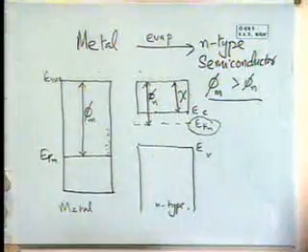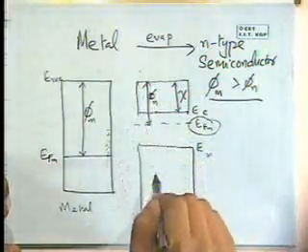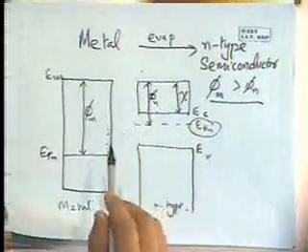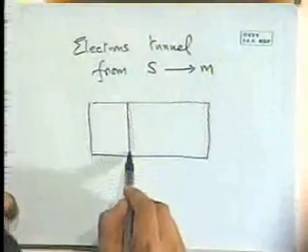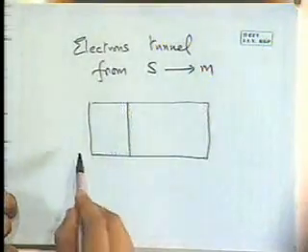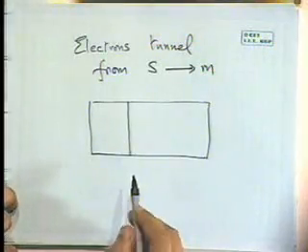So where is the positive charge, in the conduction band or in the valence? No, you can't show that in the conduction band or valence band. It is in the semiconductor. So I will not sketch it into the band diagram, but more if we do, I'll sketch that in a second. If we simply look at the semiconductor metal interface, I am drawing the metal thinner because typically the metal is orders of magnitude thinner than the semiconductor.